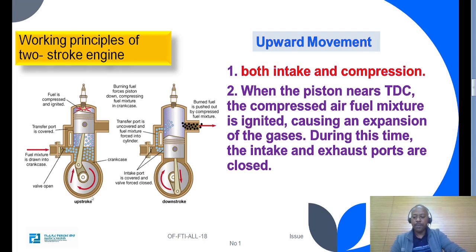So this is the up stroke. In the up stroke, in the lower part, intake of the combustible substance is taken, and in the upper part of the engine, compression of the fuel mixture takes place. Also when the piston reaches TDC, ignition is commenced.